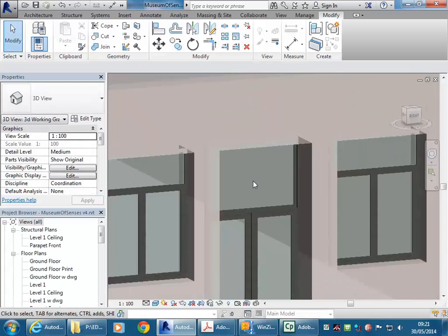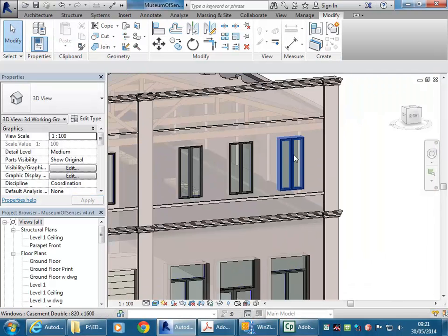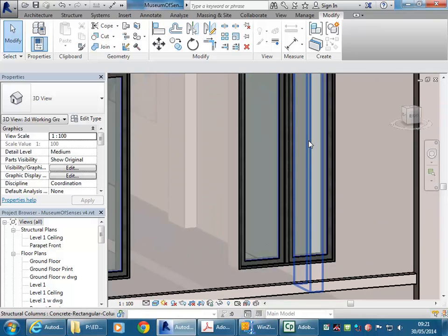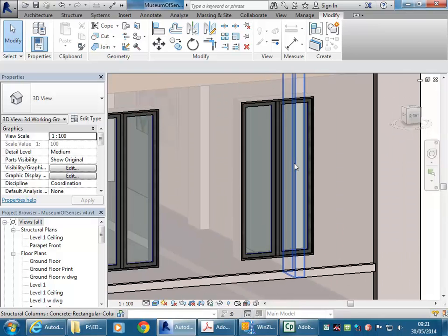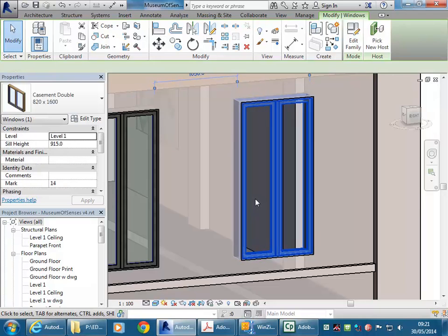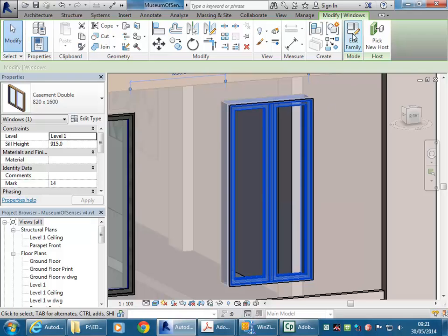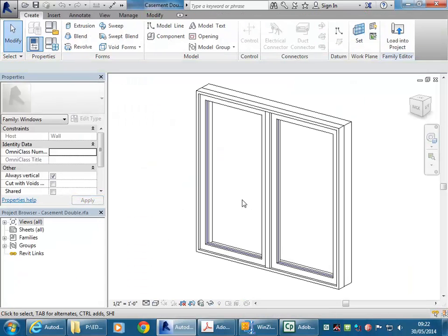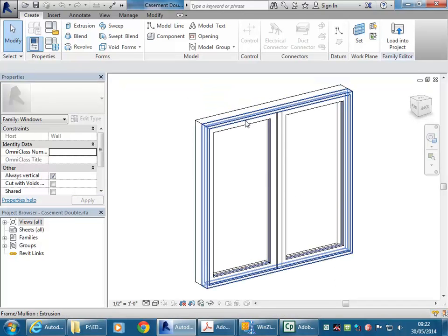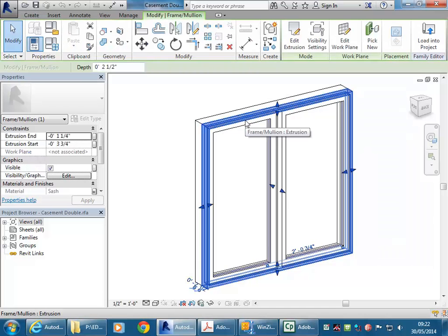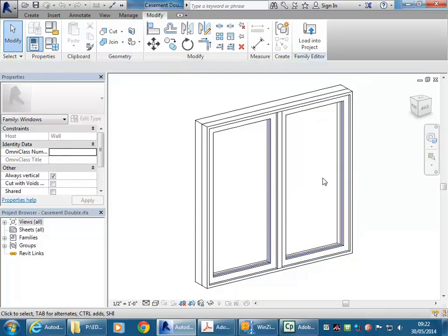my new one. So I've made an adjustment to that family and basically deleted the trim, which is something you'd probably want to do with most of the window families that Revit gives you. They're done the American way, which is to often have architraves on everything, and you definitely don't want those on this building. So again, I'll show you that family. You won't need to do anything with that, but if you do want to change families on your own, it's easy to open them like this and just delete the parts that you think are causing a problem.